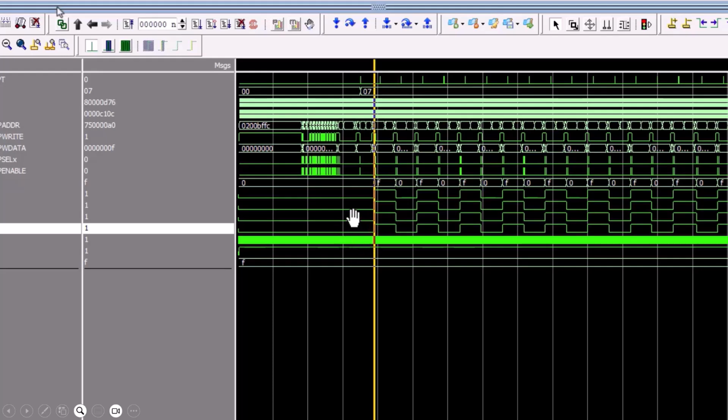A moment later, this entire sequence repeats. The same instruction address and the opcode execute again. The same GPIO address is written to, but this time GPIO out goes to 0x0 and all four LEDs are turned off. This toggling pattern between 0xF and 0x0, repeated with each interrupt, is what creates the LED blinking effect in simulation.